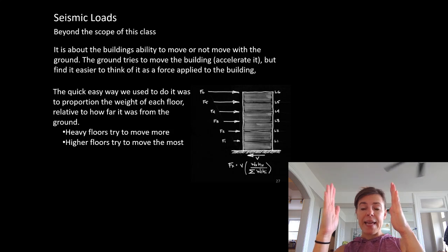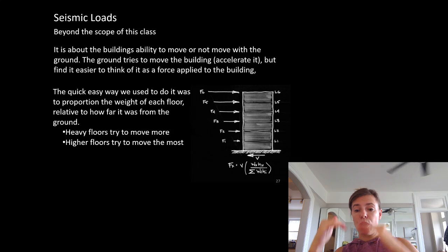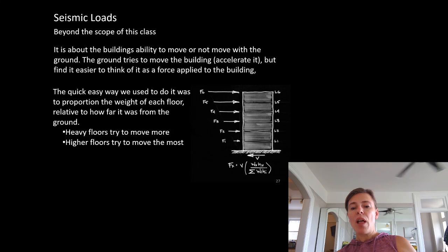What we say is, as our building moves, we will allow that movement to actually reduce the load our building sees. In Toronto, often we don't do that because seismic doesn't tend to govern, or if it does, it's a reasonable design, and the cost of the extra material to build it is not offset by the engineering costs.